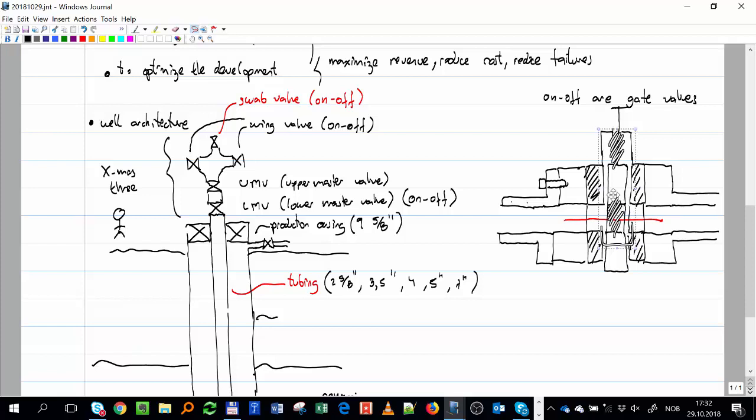So what is something very important about a gate valve, about on and off? It should always be fully open or fully closed, or it should be closing or opening. You shouldn't leave it midway, because otherwise you create too much friction in the area where you have the seal surface, and you might destroy it. That's actually where you have all the seal, what is protecting the rest of the system. So let me just put it here, and here I can bring it up and down.